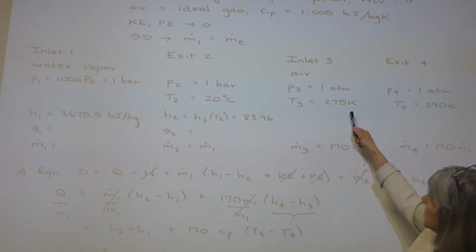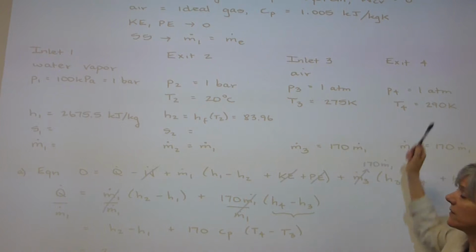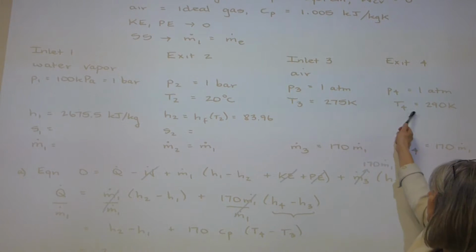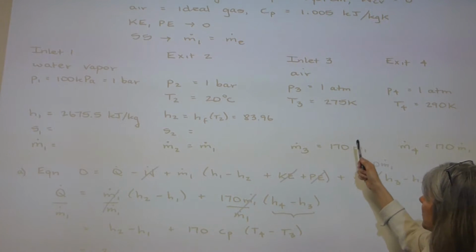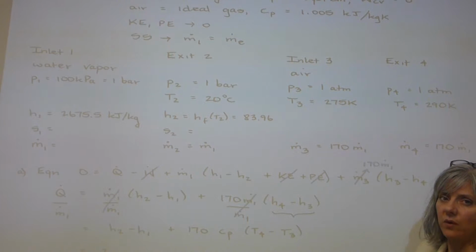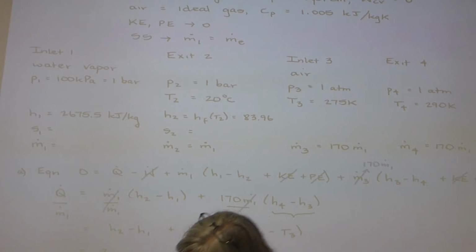And the reason why that is actually a very reasonable thing to do is that this is only very slightly different. So if I look at the C sub P values, they are dramatically the same between these two. When the temperatures are much further apart, then we have a problem because then the C sub P value varies a lot. And so that's where we end up with more error coming out of this way of doing things. Okay, so now I'm going to drop in all of the values.